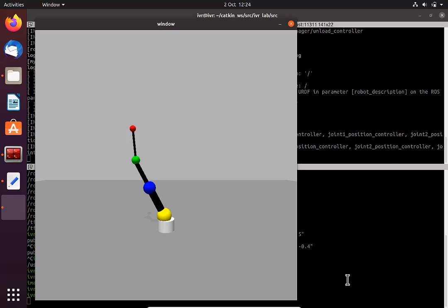This is the image that we're going to work with. You're going to use different algorithms on it to detect the joints and find their positions. For instance, in this case, I asked this joint to move to minus 0.5 radian, and this joint to move to 0.5 radian, this joint to move to minus 0.4 radian, this joint is kept 0. So if my image processing algorithm is successful, I should be able to get these joint variables and compare them with the commands that I gave it. This is what we're going to do in lab 1 and 2. And in lab 3, once you're more familiar with this environment, we're going to use these joint measurements to move the robot on a specific trajectory that we want.